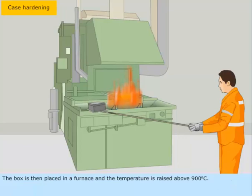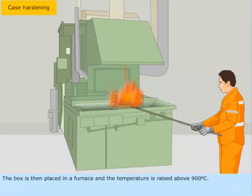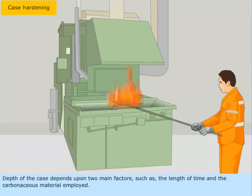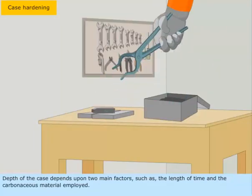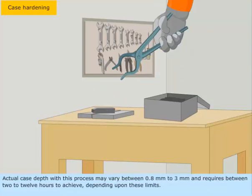The box is then placed in a furnace, and the temperature is raised above 900 degrees Celsius. The surface of the component will absorb carbon, forming an extremely hard case. Depth of the case depends upon two main factors, the length of time and the carbonaceous material employed. Actual case depth with this process may vary between 0.8 mm to 3 mm and requires between 2 to 12 hours to achieve, depending upon these limits.